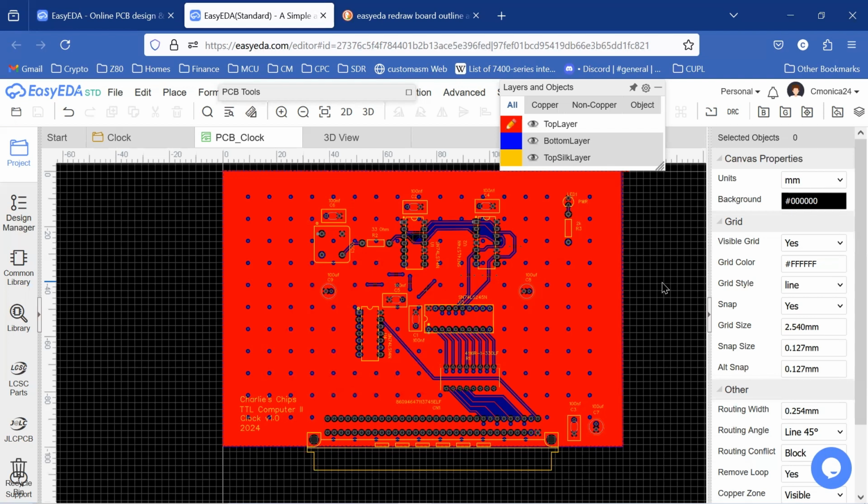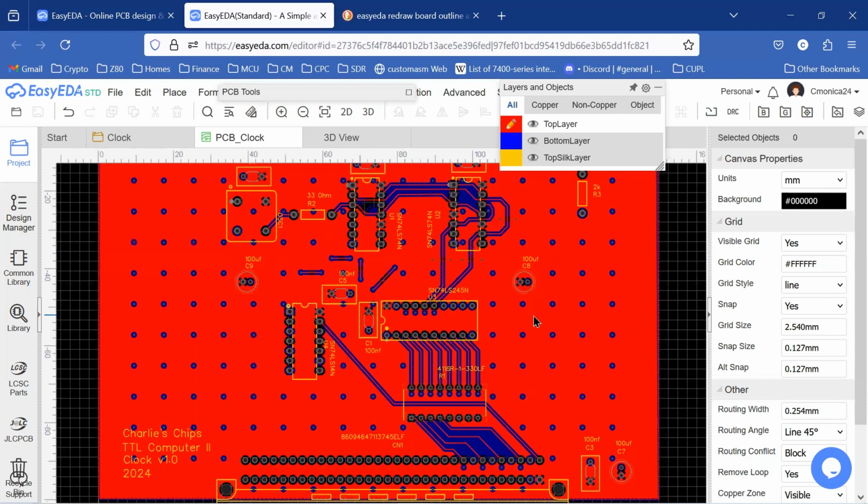But now when I did the routing here, I placed the components on the board manually, and I arranged those to something that gave me like a good starting point. And then I did auto trace routing, and that was okay. But I ended up doing maybe 50 or 60% of the routing again by hand to get to what you're seeing now. And yeah, you're pretty much recommended to do manual routing.